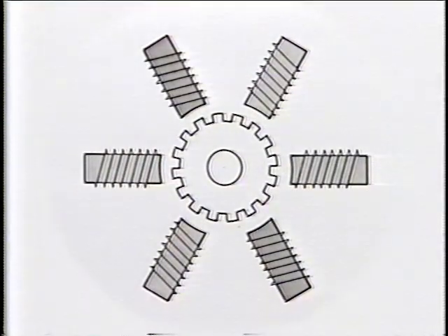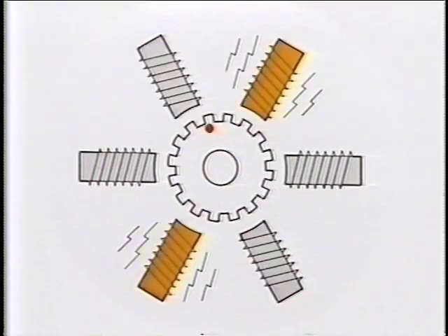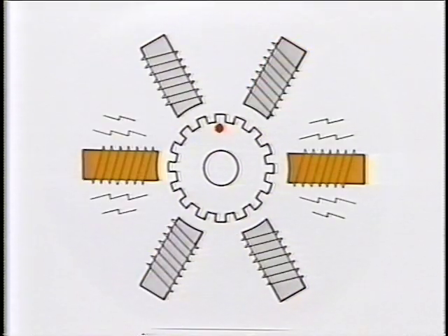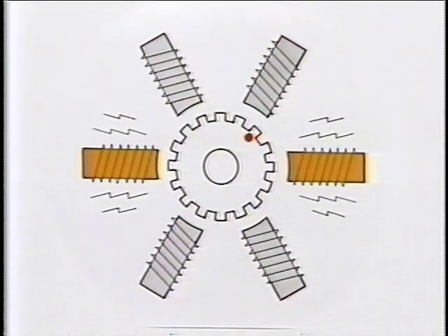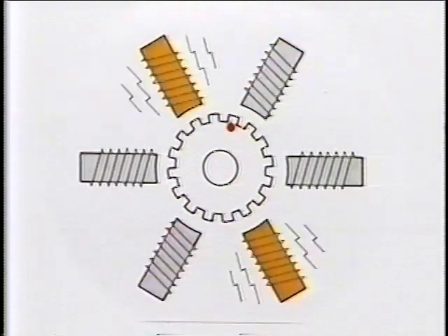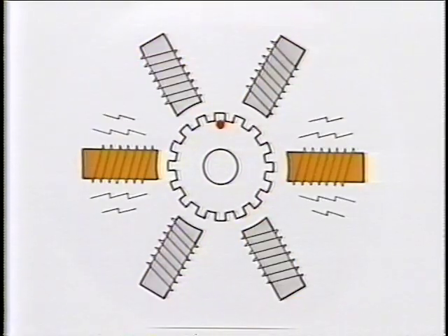Inside a stepper motor are a number of wire windings which surround the rotor. The rotor and the shaft turn as one unit. The motor is electronically driven by energizing one set of windings at a time, sequentially, in the direction the rotor is to turn. A stepper motor can be prevented from turning electronically. We call this the detent mode. This is done by keeping one set of windings energized.